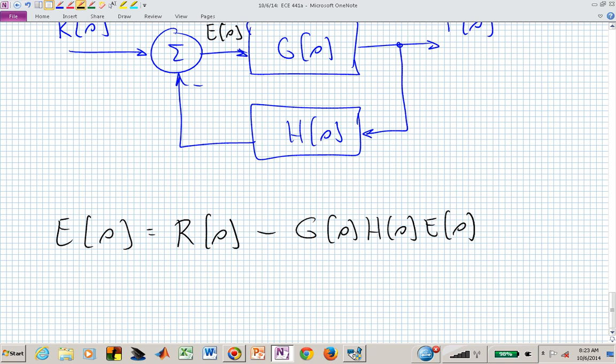And we are adding and subtracting signals. We have a signal E, we have a signal R, and we have a filtered version of E. E is filtered through the plant and this feedback path H, which might be a controller, it might be sensor dynamics, and G may actually be a collection of our system and a controller. If we dig into it, it may be more involved than just that one transfer function. This we should be comfortable with.